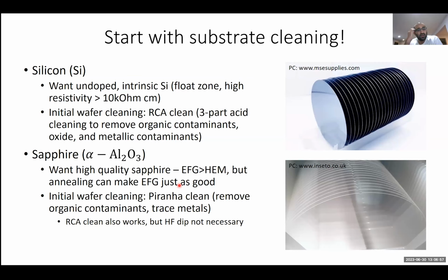I'll also say that if you don't want to do an acid-based clean, you can also just do a solvent-based clean, just using regular organic solvents like NMP, acetone, isopropanol. But it really seems that if you want to get the cleanest wafer possible, you should do these more aggressive acid-based cleans.